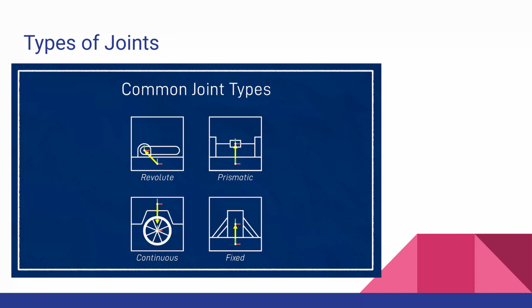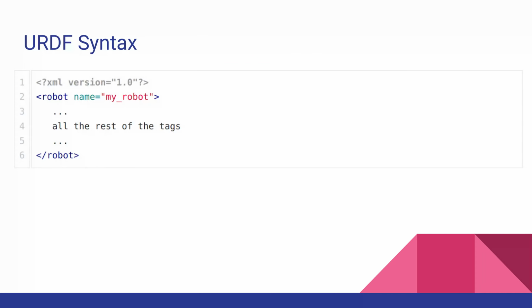We'll expect that the wheel might rotate by many rotations, so the degrees or radians will be very high in that case. However, in the case of a revolute joint, we can measure angular differences in terms of degrees or radians. So suppose I have a robotic arm which cannot go beyond a certain angle, we'll generally describe it using a revolute joint.